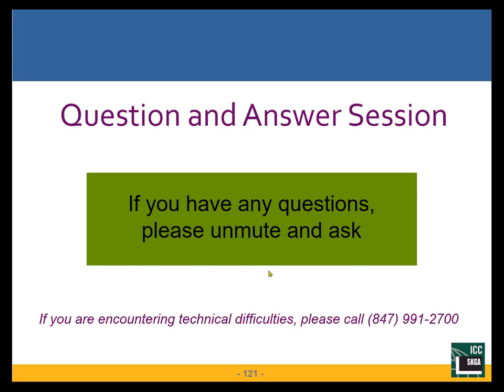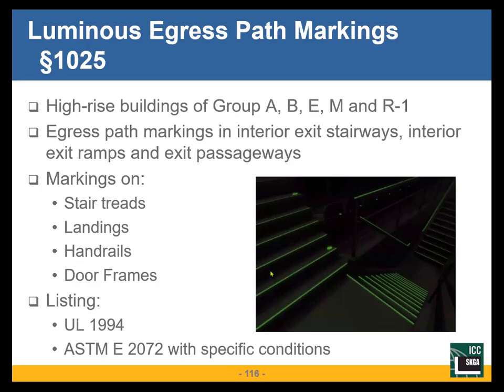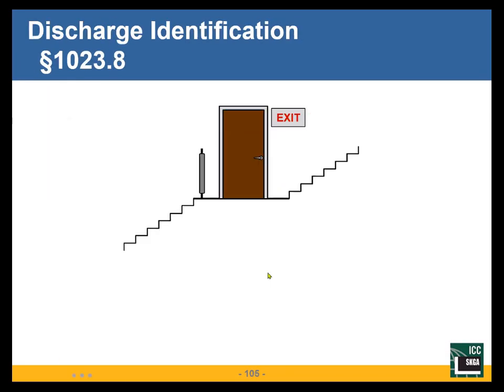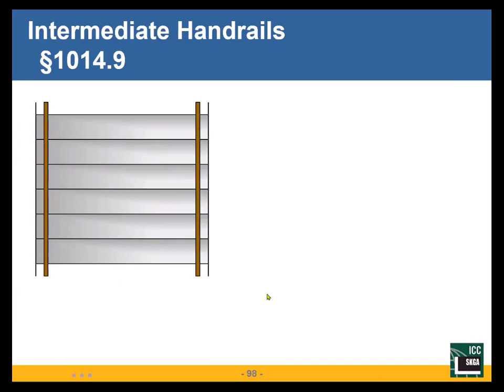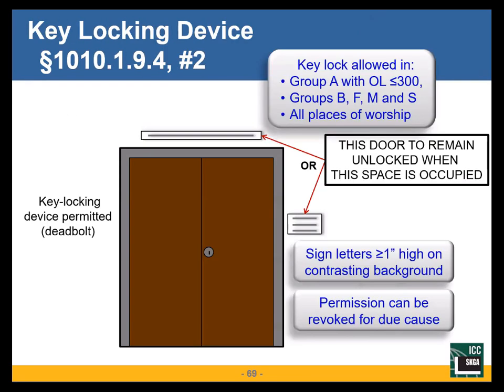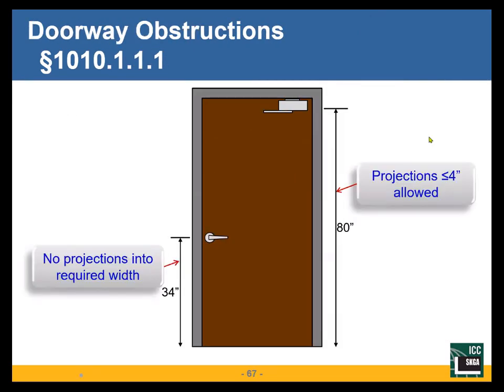That area would be standing space at 7 square feet per person. So I'd calculate the standing space and I'd add what I counted for my fixed seating. That would be my occupant load for that area. But then I also have an occupant load for the kitchen. What's my occupant load in the kitchen? So that would be how I would evaluate that.